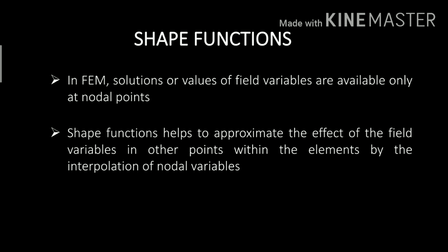Today in this lecture we are talking about shape functions. In FEM, solutions or values of field variables are available only at nodal points. Shape functions help to approximate the effect of the field variables at other points within the elements by the interpolation of nodal variables. So basically we are talking about an interpolation function.